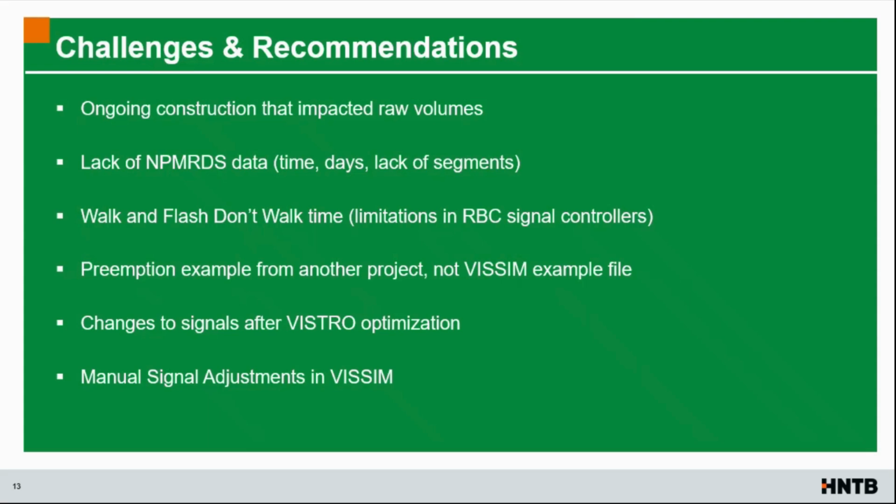Walk and flash don't walk time. There was a limitation in the RBC controller. I think it has been taken care of. It was one of the challenges that we faced, and thank you to PTV Group for fixing this. Before that, we had to limit the green time of the parallel movement to the pedestrian movement to the flashing don't walk time and walk time in total. So that has been taken care of.